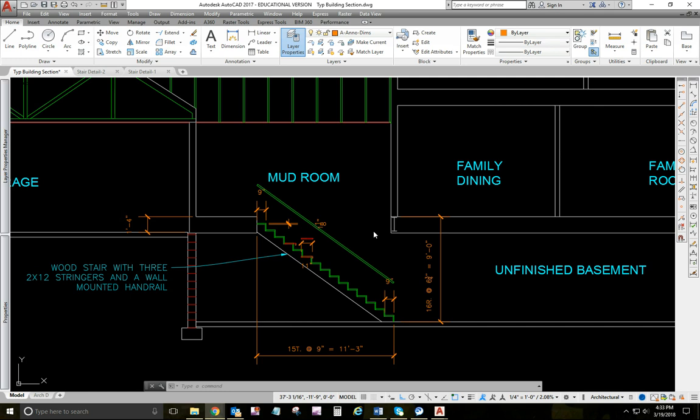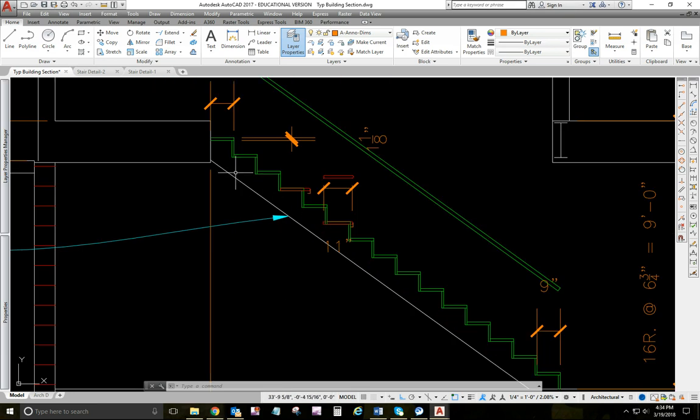Anyway, you can be reading through that chapter on stairs, and there's a number of different ways to calculate the riser height and the tread size. We're going to use rule number 4 so that we're consistent and it makes it so that I can ask you a question on a quiz and then you can make the calculation and answer it and come up with the answers.